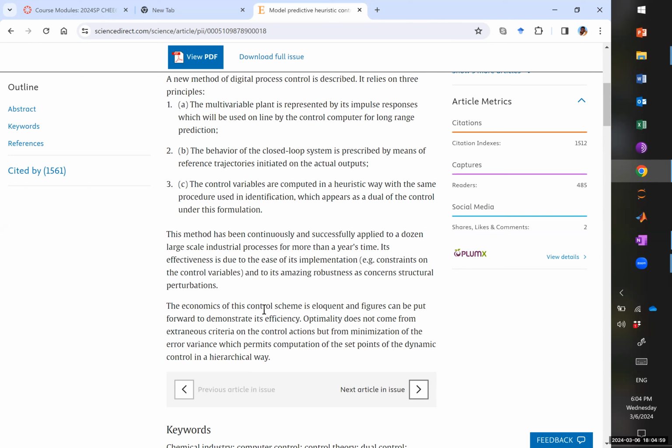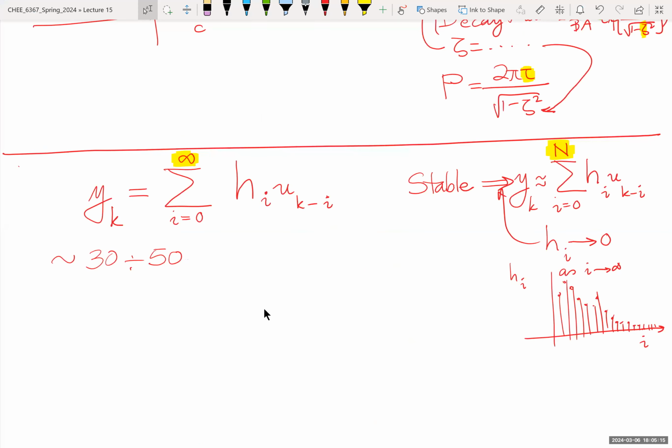Shifts can be 8 hours or 12 hours, those are standards in industry. So from one shift to another, I may have roughly steady state values, give or take. And people optimize these steady state values by a technique called real-time optimization, or RTO for short. This is usually done over steady state.